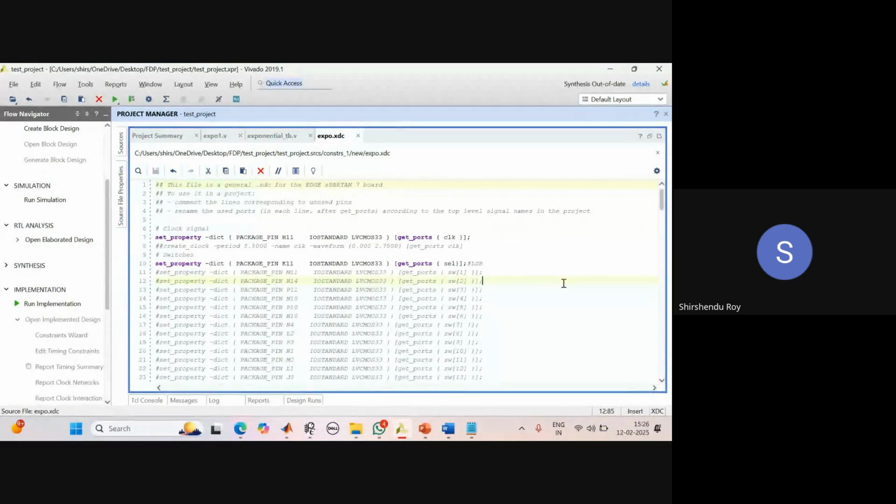Now everything is done. But initially, I will not implement on the hardware. Before that, I need to perform the implementation, and I also have to obtain the performance. So for that, I will uncomment this line. This line is very important. It is saying to use a clock period of 5.5 nanoseconds and a duty cycle of 50%. So your clock period is now 5.5. Okay. So make it a round figure, make it 5, and 2.5 for the duty cycle.